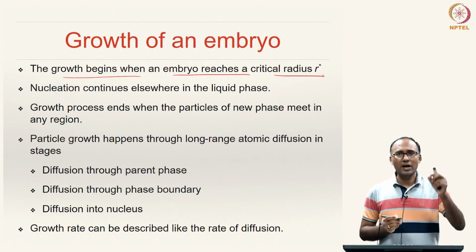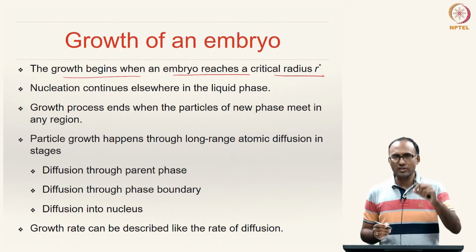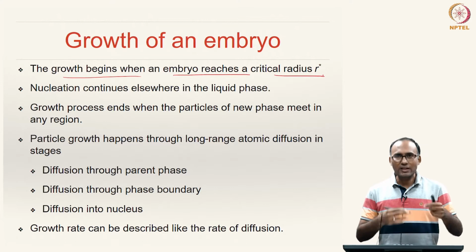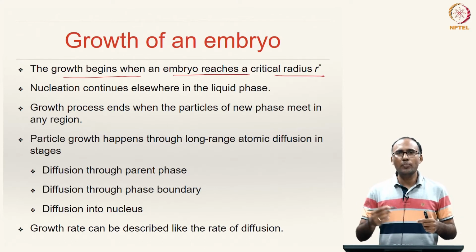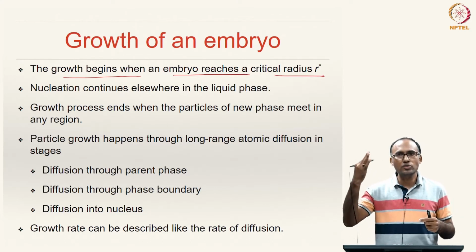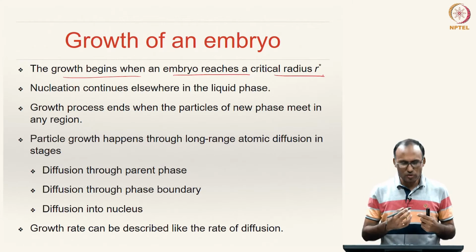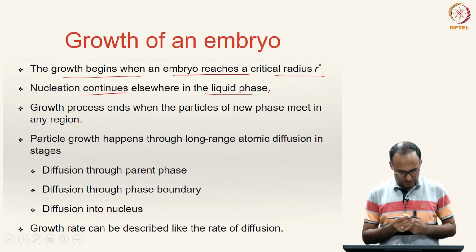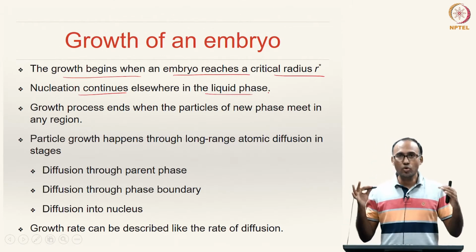So, once you have a certain nucleus formed at one place in the liquid solution, while this is growing, it is still possible that nuclei can continue to form at other locations, right. So, they can happen simultaneously. So, the nucleation continues elsewhere in the liquid phase, and however, this growth process ends.